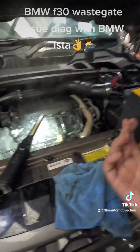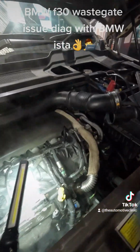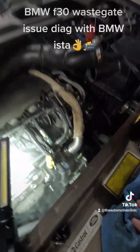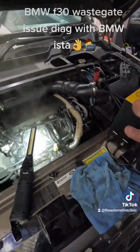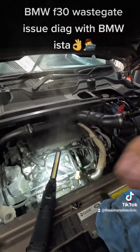This car was sold by a car yard, I believe, came back and has been sent around the ring a bit, but we've got a boost leak. This thing is going to need a new boost hose. Once it's got that on there, all the adaptions can be done, it can all be reset, and it should be good to go.